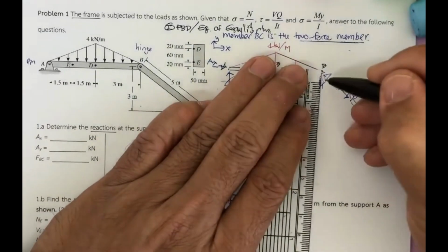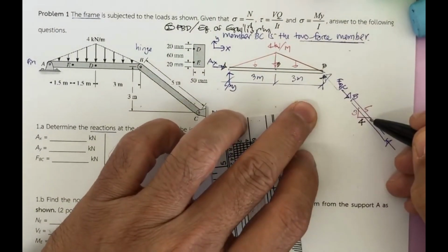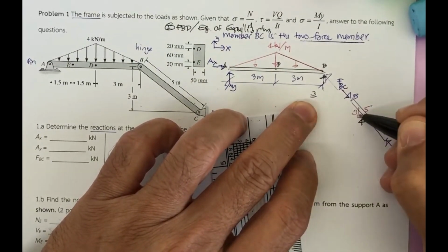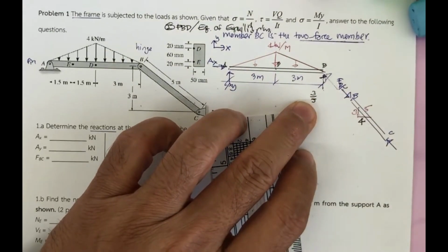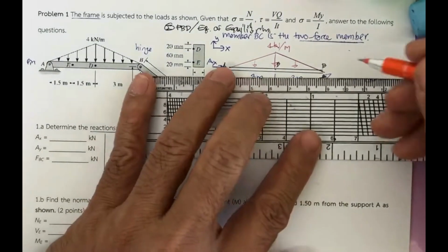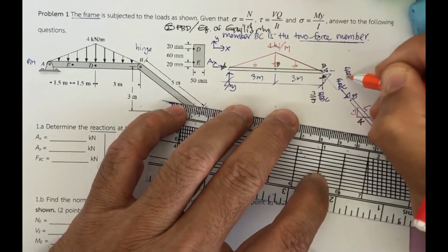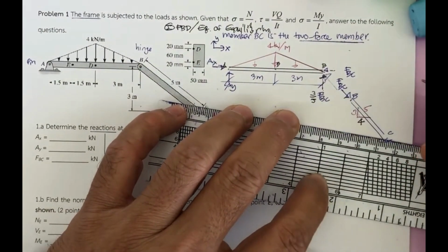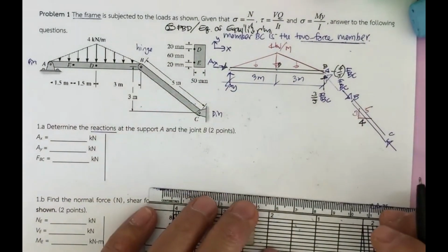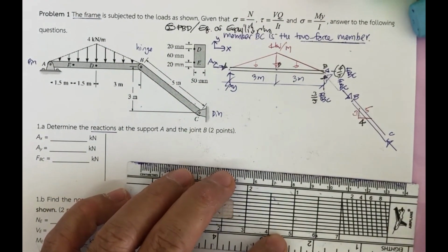And also, if you go further, the force F sub BC here is going to be what? We separate it. This is in vertical. This is 3, it's going to be 3 over 5 F sub BC. And in another direction, here in horizontal direction, it's going to be F sub BC, and then this is 4. It's going to be 4 over 5 F sub BC. Okay, that is going to be a very complete free body diagram of this.